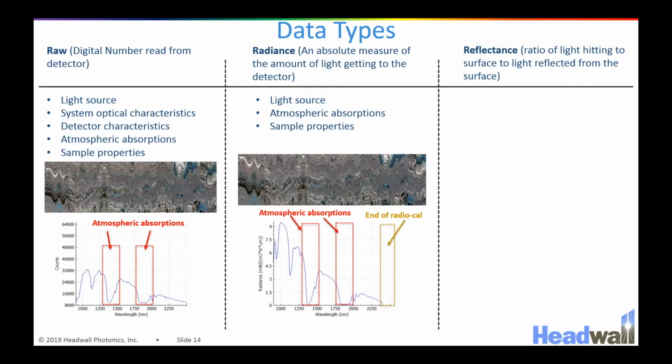This must be done with the whole system altogether. So the radiometric calibration calibrates for a specific lens. So we will need to put the lens that you want calibrated onto the system and then run it through our calibration procedure. And the radiometric calibration will be a measure of actually how much light is reaching the sensor per solid angle.